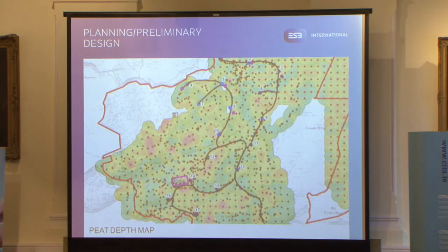A huge part of what we use Civil 3D for in wind farm design has to do with peat stability and peat excavations. It is incredibly important to factor in peat into our 3D model prior to our design. Once a greenfield site is presented to us for assessment, the overall goal is to obtain as much ground investigation data as possible to inform the site design, such that access roads are located to minimise peat excavations, etc. At planning stage for a wind farm, we typically carry out probing on site on a 100-metre grid.